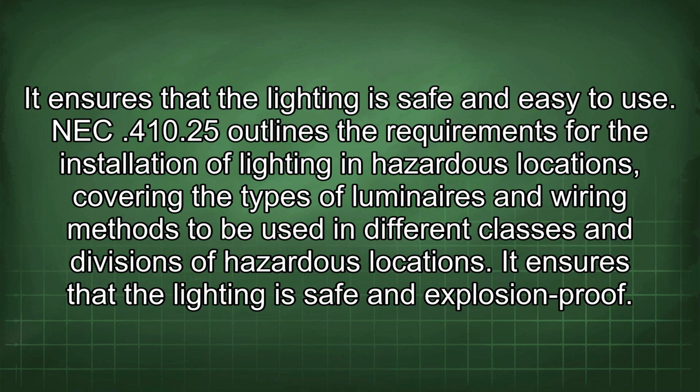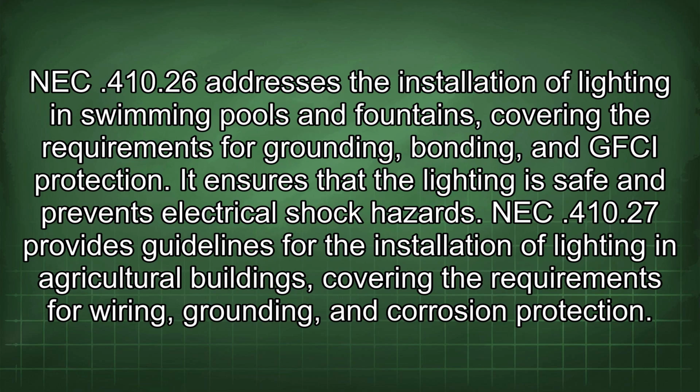NEC 410.25 outlines the requirements for the installation of lighting in hazardous locations, covering the types of luminaires and wiring methods to be used in different classes and divisions of hazardous locations. It ensures that the lighting is safe and explosion-proof. NEC 410.26 addresses the installation of lighting in swimming pools and fountains, covering the requirements for grounding, bonding, and GFCI protection. It ensures that the lighting is safe and prevents electrical shock hazards.